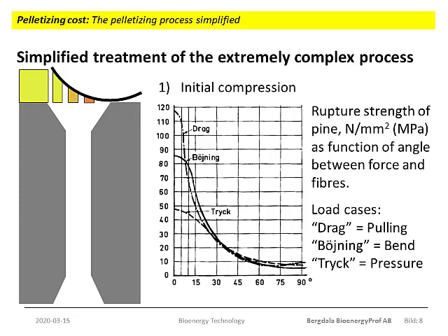The diagram in the slide illustrates the rupture strength of Scots pine, Pinus sylvestris, at 10% moisture quotient. You will remember that the moisture quotient is the moisture content on a dry basis. So the moisture content, as we generally refer to it, the wet basis, is a bit lower, about 8%. The x-axis in the diagram is the angle between the applied force and the wood fibers.